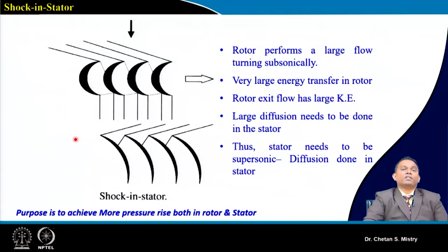Now there are other configurations in which we will have shock in the stator. You can see here, this is a kind of aerofoil for the rotor. A whole lot of acceleration, or large turning of the flow, is happening inside the rotor. When the large turning happens, the exit kinetic energy comes out larger.